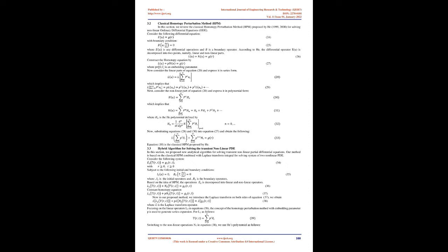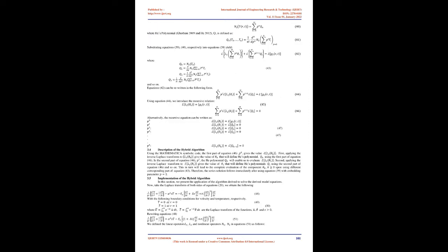The first mathematical model of blood as a third-grade non-Newtonian fluid was started by Mehi et al., 1994. Their model involved pulsatile blood flow subjected to externally imposed periodic body acceleration. The equations that described the flow of blood are strongly nonlinear and were solved numerically using an implicit finite difference technique. In this model MHD was not taken into account.